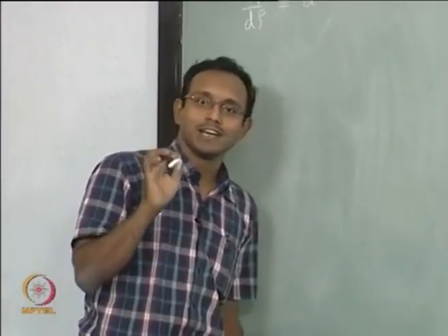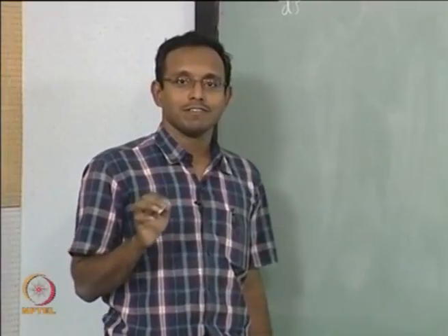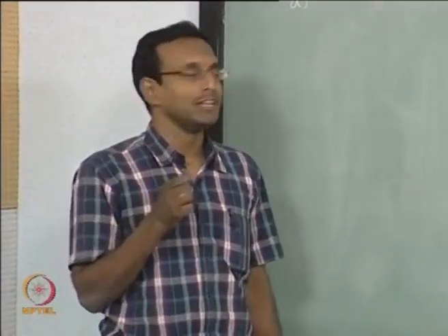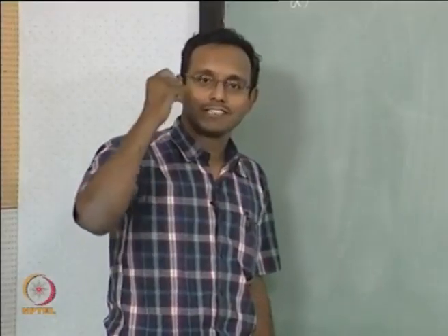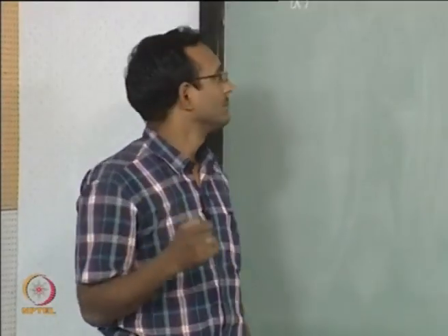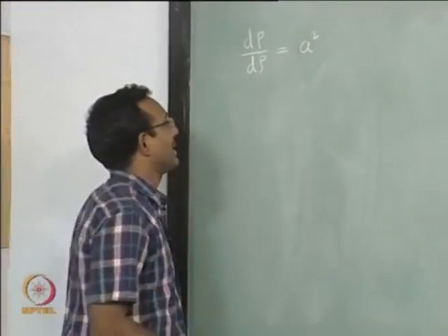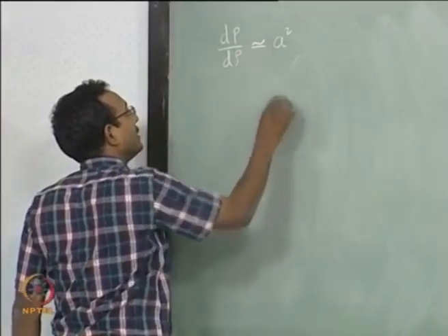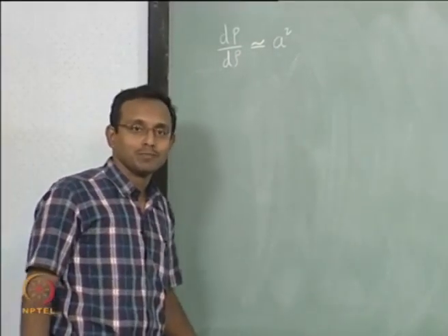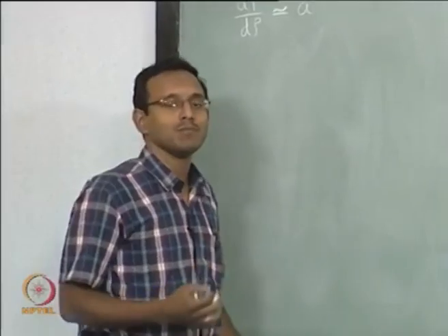I am going to use that argument and say the change caused by this wave is almost 0, the du, d rho, dt, dp, whatever we had in the last board, everything is almost 0, that is what I am going to say. If it is almost 0, then I am going to say this is dp by d rho is almost equal to speed of sound, because the expansion wave moves or behaves as if it is a sound wave, almost a sound wave.